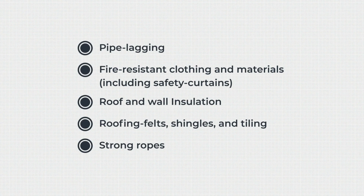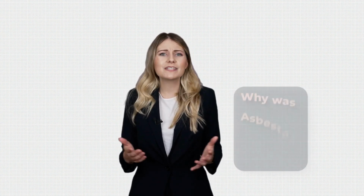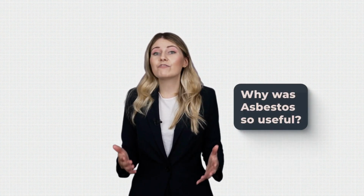For some time, traces of it could also be found in unlikely products like talcum powder, crayons, ironing boards, and even some alcoholic drinks. But despite being dangerous, why was asbestos so useful? The main reason for asbestos to be used in such a high extent in construction work was due to the natural heat resistance and strength. It was cheap, durable, and didn't have to be treated before it was used to enhance its properties. The fact that it bonds easily with other materials and was plentiful also made it a highly profitable substance.